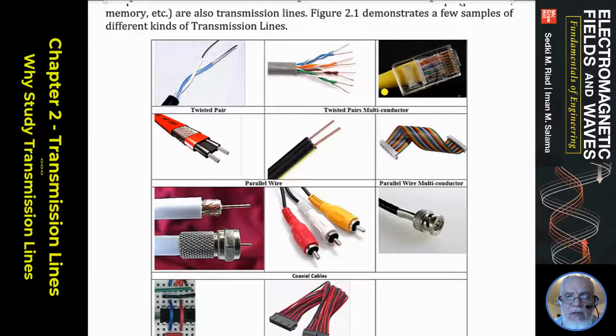All these are sort of what we may refer to as control geometry transmission lines. And the point is, if you go in the cross section of the arrangement here, it should be the same everywhere. In other words, the cross section is controlled, the spacing is controlled, the material isolating them is controlled, so it's controlled everywhere. So the length of the wire is kind of uniform.